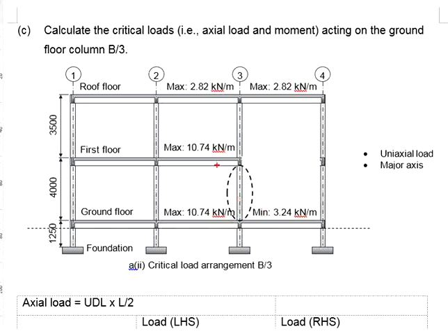To determine the moments taken by the column, we will need to first get the stiffness of the column and then the total stiffness of all members at the joint. Whatever moment acting onto the joint here, which is as a result of the fixed moment caused by the UDL loads acting onto the beam here, this moment shall be shared among all the members connecting the joint.